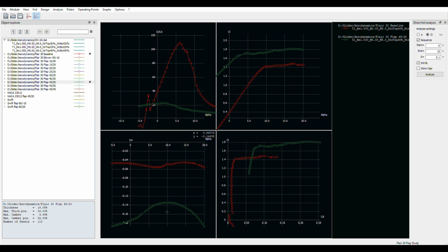I'd have to go do those runs, but I already know the final answer, so I'm not going to do those runs. We do see pictures of the Flair flying nicely with the flap down. Different flights, different angles. Very difficult to ascertain what the actual angle of the elevons are. It appears to me that the elevons are up. We just don't know how much. And that's because the elevon and flaps are butted right together, and we tend to look at the V-shaped open area between the flap and the elevon and judge an angle from that. We don't know how much of that angle is due to flap and how much is due to the elevons. So we really don't have a good measurement on that.